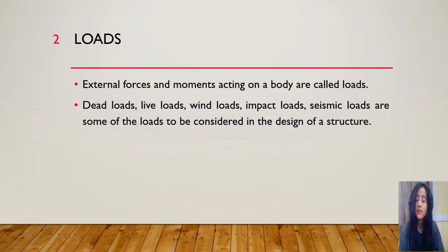Then we can even consider the workers who are constructing the building and workers who come for maintenance of the building. These are also live loads because they keep on moving. And other loads such as snow loads, wind loads, seismic loads and impact loads, all these loads also come under live loads because they are not permanent. They come temporarily. So a live load can also be expressed as a uniformly distributed load, UDL, or as one acting on a concentrated area, which is a point load.